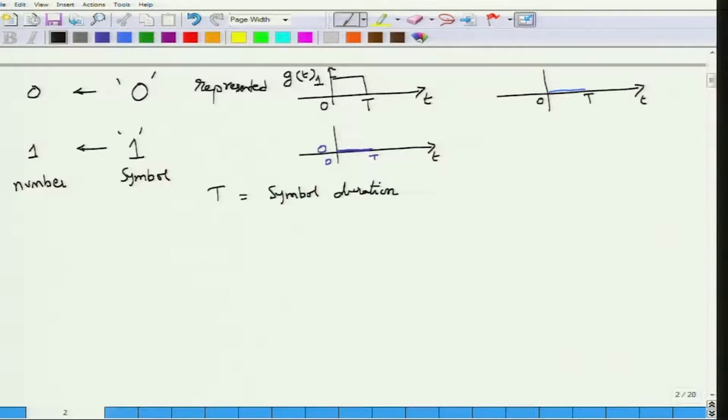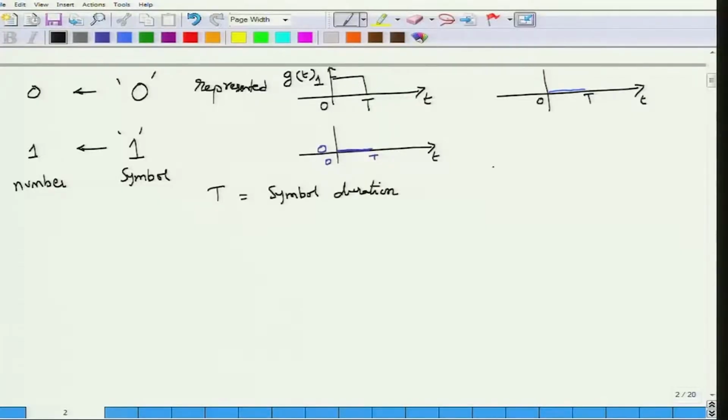Now these waveforms, are they ready to go on the optical fiber? Well, not quite yet, because we have these waveforms in what is called the baseband domain. Okay. In the baseband domain, the frequency content is mainly concentrated at the 0 frequency. Okay. But if you want to transmit these symbols, or these waveforms, over optical fiber, what you would have to do is to transform this baseband into what is called pass band, or band pass sometimes. Okay. So, you want to transmit this into pass band.